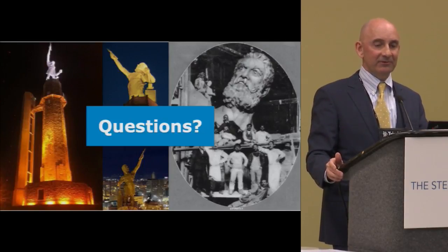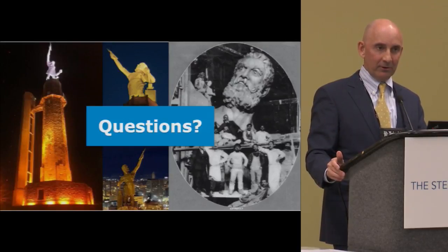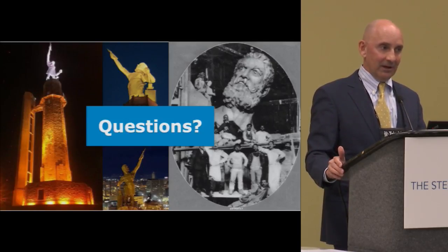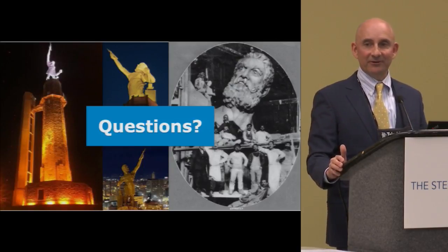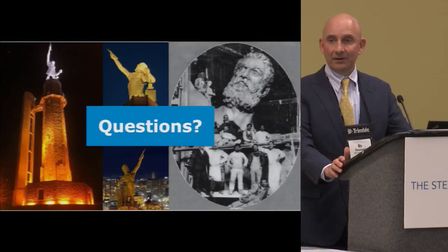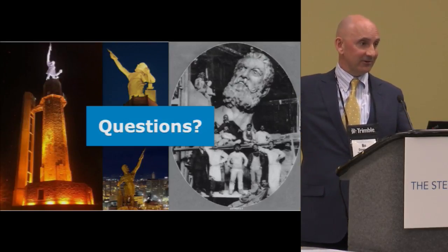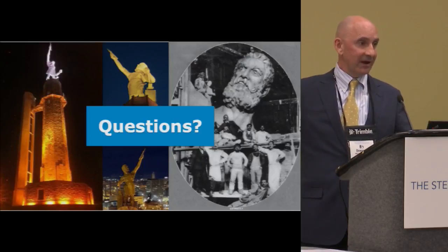In fact, I believe there's a paper that's either already been published or about to be published on stability of rectangular connection elements. It goes through and explains where you can and can't use those plastic interaction equations, and then it gives you alternative equations when stability does come into play. And it complies with this too, because it gives a straight line interaction when stability is critical for both the moment and the axial.